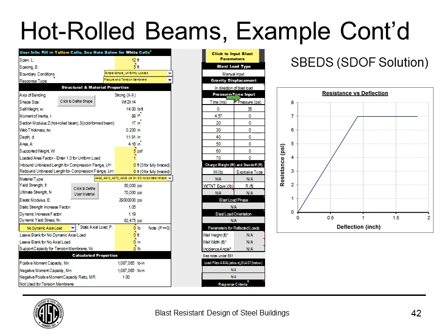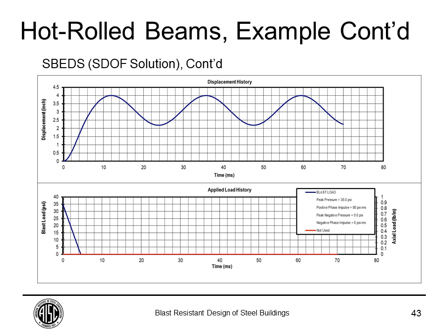In this middle area of SBEAT, we can enter the load. You can see it's the same pressure and impulse and duration as we had before. And then you run the time stepping solution, and we get the same load right here. You compare that, make sure that you put your load in right, and we can see that the maximum deflection is about 4 inches. So it's a little bit less than what we calculated with the energy solutions.